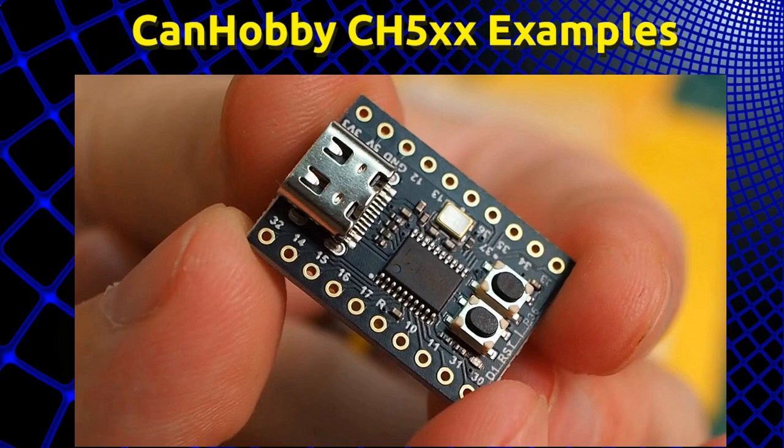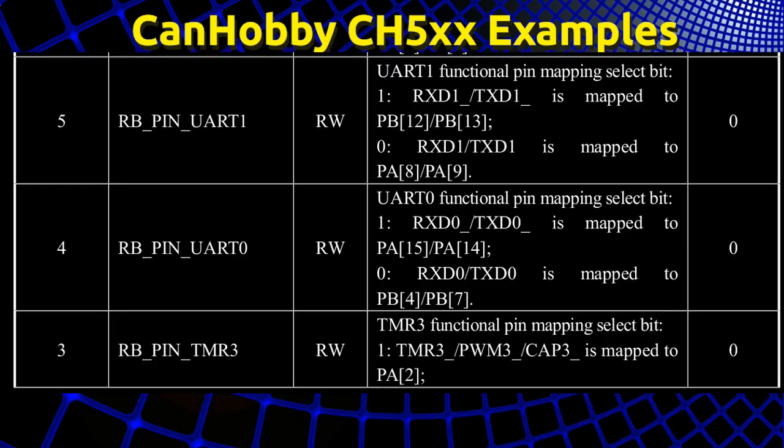I found that I needed to do this after reviewing the I/O that I wanted to use for this project, and carefully reviewing the documentation for the microcontroller I'm using. My constraints were not to use PA8, where the onboard LED is connected on many boards, as well as to be able to use SPI0 for the megapixels. We also need to be aware of the USB pins so as not to interfere with uploading during the development process. I also want to try to use a WCH Link-E programmer on my own board designs.